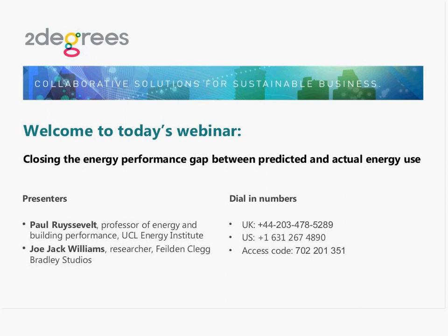The prediction is not necessarily very good, but it's been done to a particular standard of calculation. Also, taking their floor area from one of those certified sources gives you more comfort that it is a realistic floor area. That's obviously quite an important factor, because in comparing buildings with each other, we're comparing them in terms of kilowatt hours or kilograms of CO2 per square meter of gross internal floor area. And of course, if floor area is wrong, then those calculations are wrong.